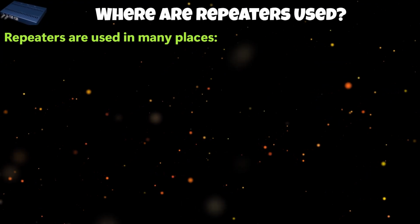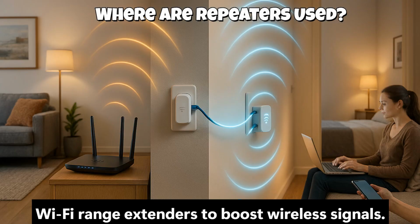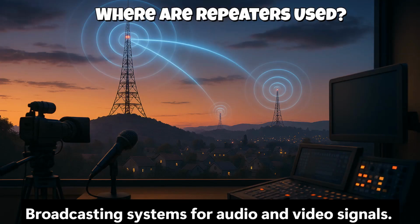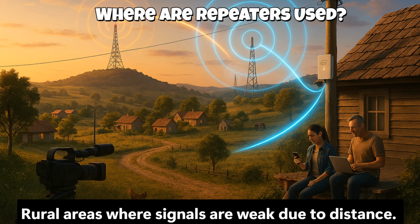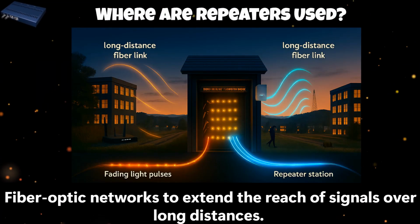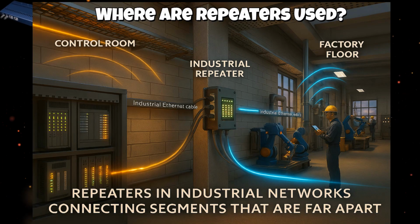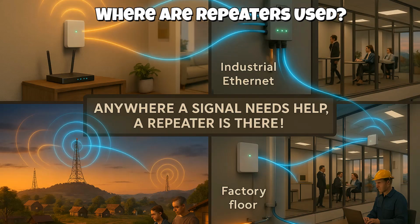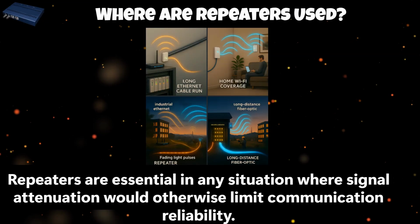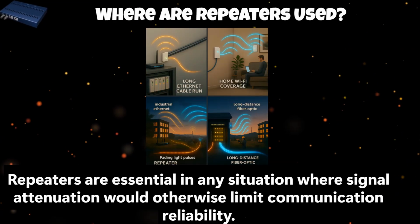Where are repeaters used? Repeaters are used in many places. Long Ethernet cables that go beyond 100 meters. Wi-Fi range extenders to boost wireless signals. Broadcasting systems for audio and video signals. Rural areas where signals are weak due to distance. Large buildings to maintain good network coverage. Fiber optic networks to extend the reach of signals over long distances. Industrial networks to connect segments that are far apart. Anywhere a signal needs help, a repeater is there. Repeaters are essential in any situation where signal attenuation would otherwise limit communication reliability.